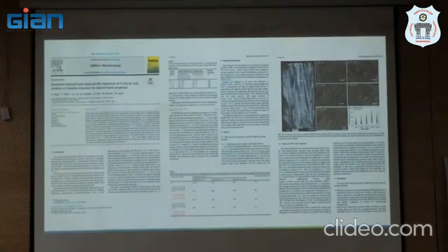The printing strategy, then reheating, and the microstructure. All the correlation is already done using the software as well as physical validation. So it is done at RMIT and available. A couple of team members were part of it. While printing, the subsequent layers go through a heat treatment, and because of that there is a grain change. Then they correlate the grain into fatigue and creep.